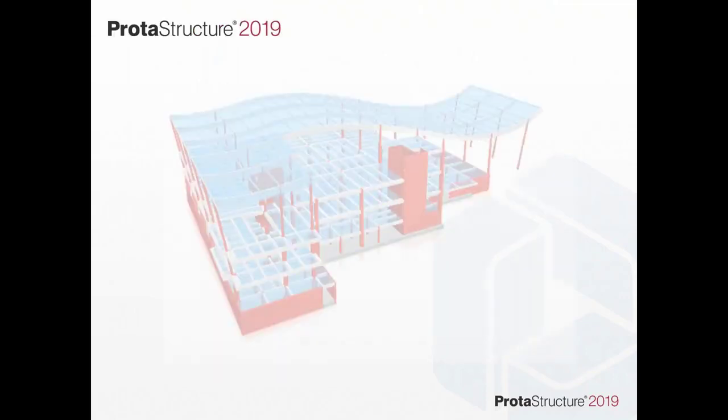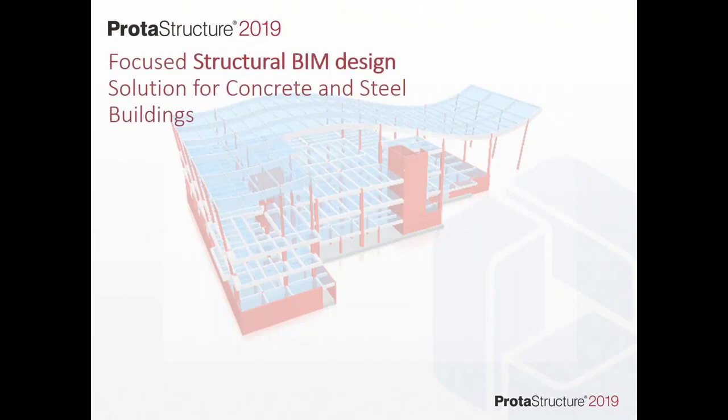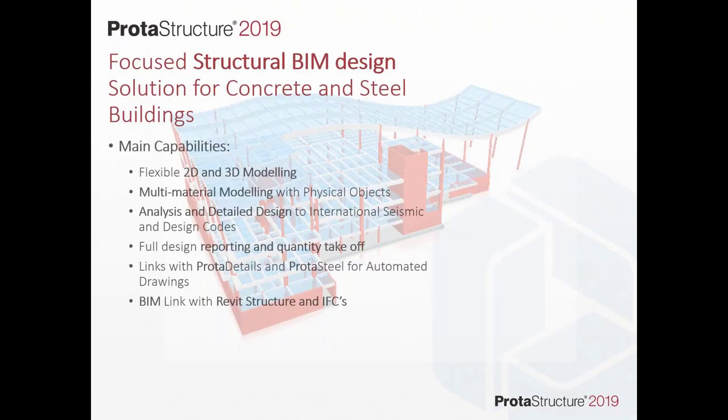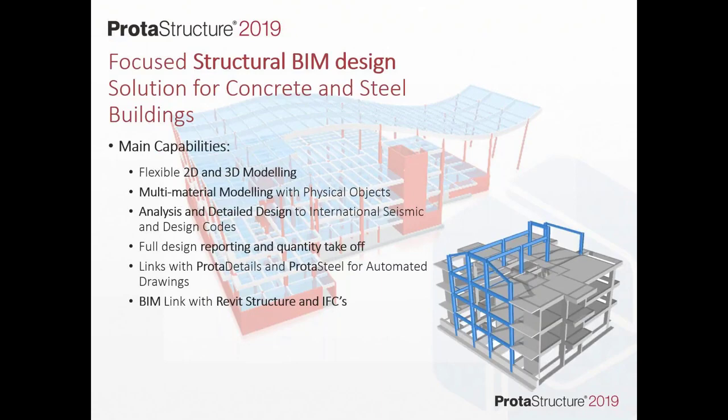But the idea with ProtaStructure is that we're creating a structural BIM design model, and this is a physical model that you can build using objects, and I'm going to work in both 2D and 3D to create these objects, and then from that physical model, we will automate much of the design and detailing process. In fact, we'll go right from the roof right down to the foundations.